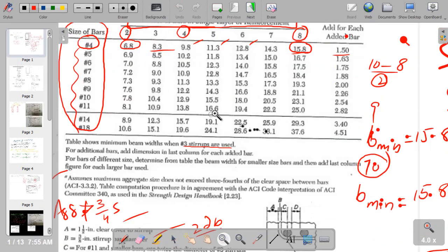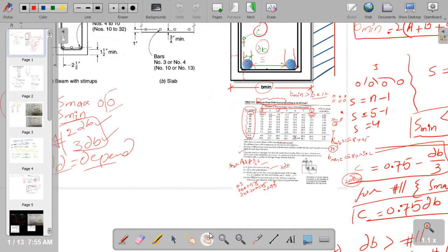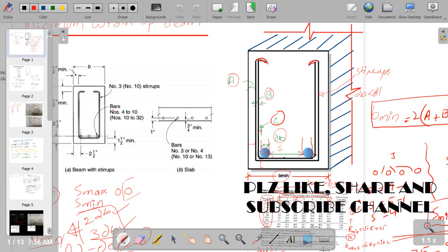So all this discussion means that we have to make sure of proper spacing for the bars, that we have to ensure minimum and proper detailing of the bars in any given section. This spacing and this kind of detailing is very important to ensure the full bond strength, because if the full bond strength is not developed, the steel bar will not yield. So for complete yielding, this kind of detailing is very important.